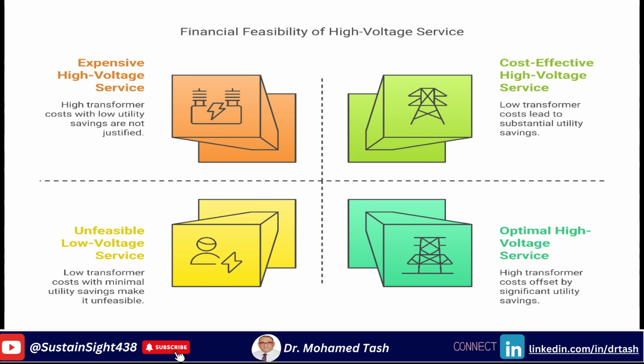Number one, the energy consumption. Energy charges are based on total energy used during the billing cycle. This is the 300,000 kilowatt hours in this example. Second, demand. Demand charges are calculated based on the highest level of electricity demand over specific time intervals during the billing cycle. This is the 1000 kilowatts in this example. Accepting power at a higher voltage can reduce the recorded demand since transformation losses from lower voltage systems are avoided.